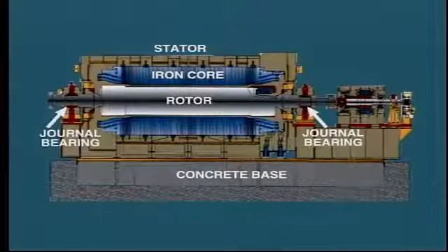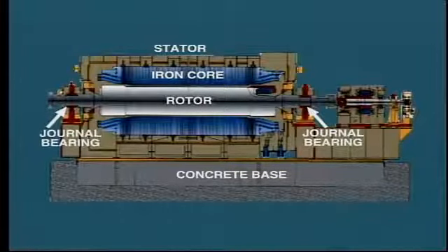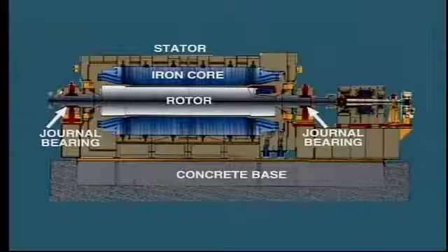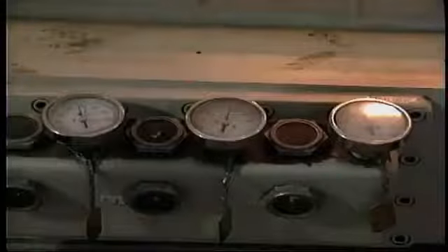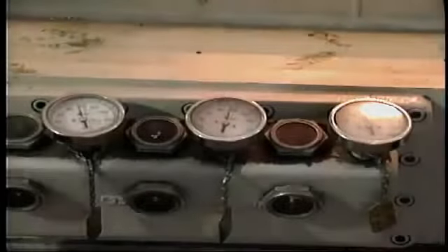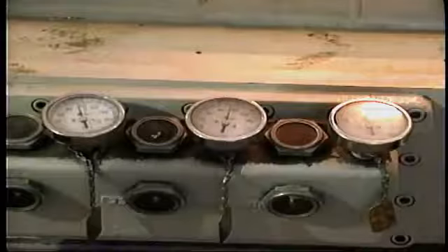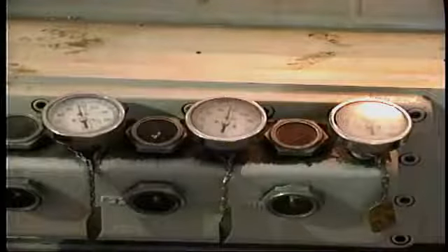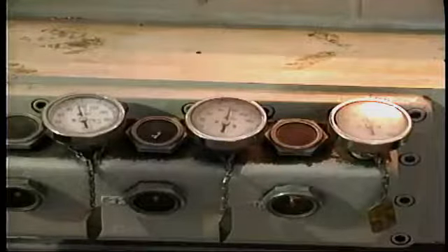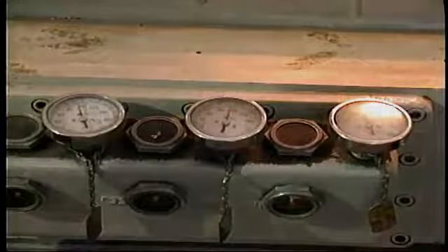These must be very accurately aligned to maintain the same precise clearance between rotor and stator all the way along the length of the rotor. A forced lubrication system is required for the bearings. Pressurized lube oil may be provided from the turbine lube oil system, or in some cases, a separate generator lube oil pumping system is installed.